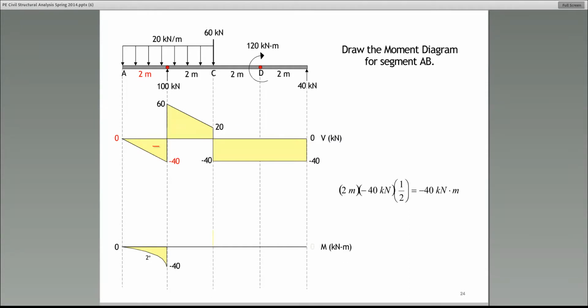Yeah, Ryan and Alan, the shear force diagram will always have to close. If it doesn't, there is something that you've done wrong. All right. So here, look at that line. It's not very crisp, but if you pay attention, that also is a parabola with a negative slope.